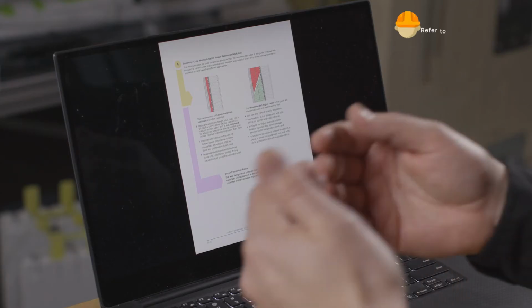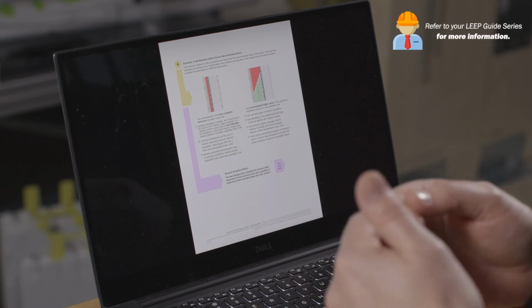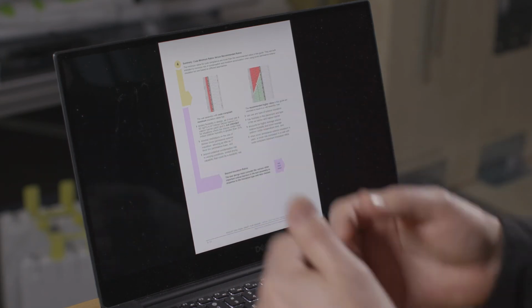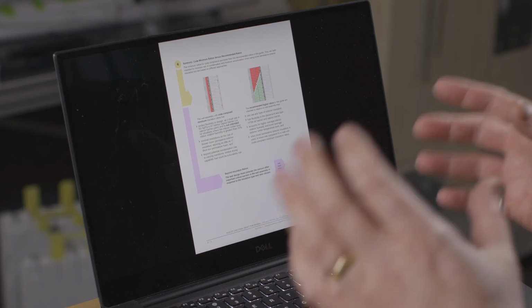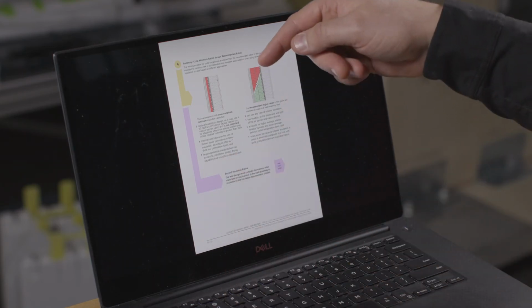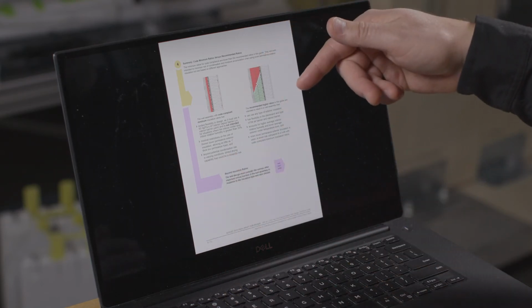The 2/3, 1/3 rule that many people have heard about in the past generally is a bit conservative, but it's a good rule of thumb as well to be safe. So you now have your choice. You have your assembly. You either have a low ratio or a high ratio, and then you go through the charts here to assess what to do for vapor control on the inside, as well as air control. So you have either low ratio or high ratio.